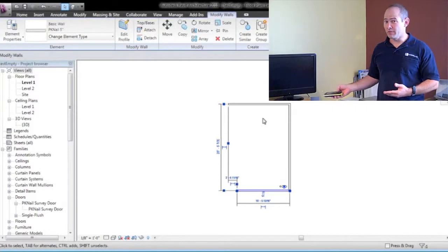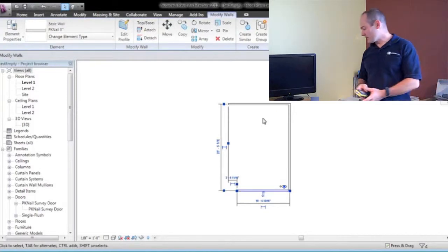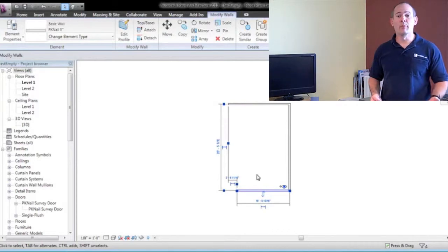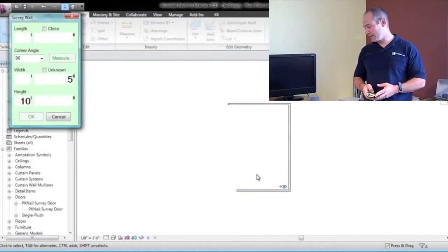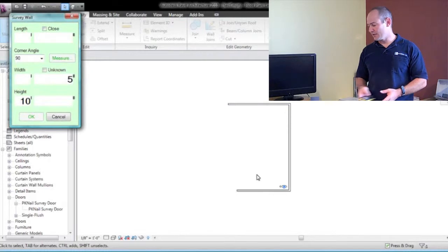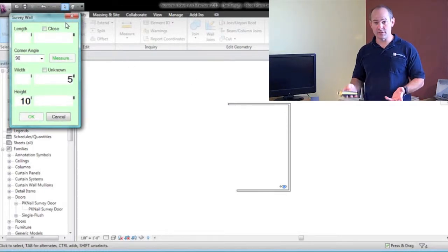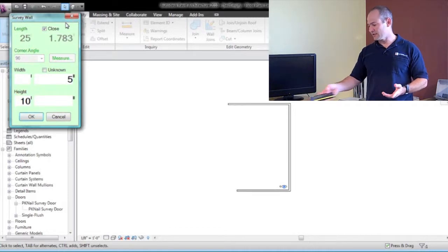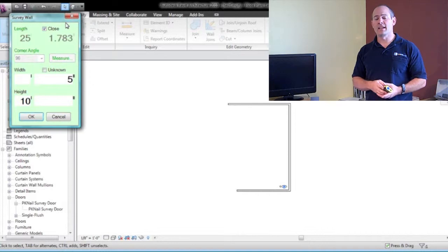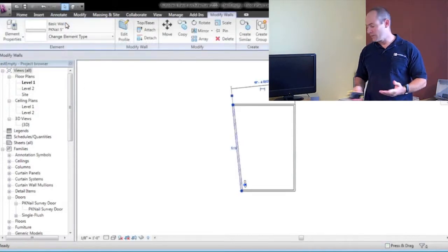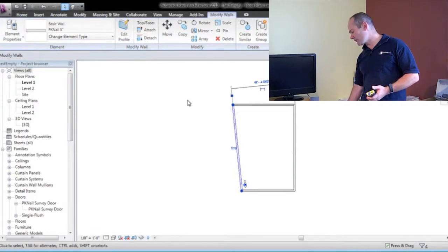and now you can see we have three walls, but these two parallel walls here are of different lengths. I bring up the Add Wall again. The first option here, if you can see, is Close. I'll activate that with the disto. The box checks, it knows the distance and the angle, and I ask it to go ahead and build that wall. And so here you have the closed room, finished, correct, dimensionally correct.